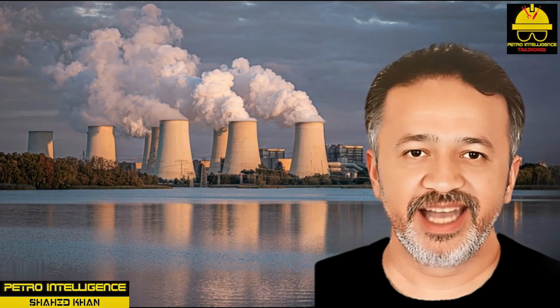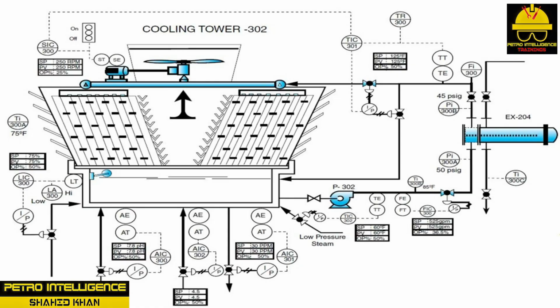Blowdown Control, AIC 301 Analytical Indicating Controller. The purpose of this controller is to monitor and control the levels of suspended solids. Using either draw-off or blowdown, this process is primarily used to control the buildup or concentration of minerals in the recirculation water. The blowdown system is designed to control the level of suspended solids in the water basin. High levels of suspended solids will cause fouling.